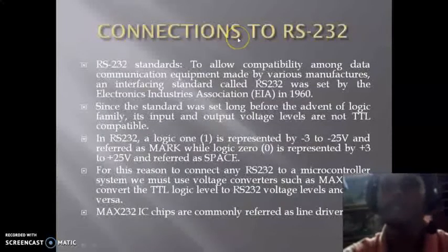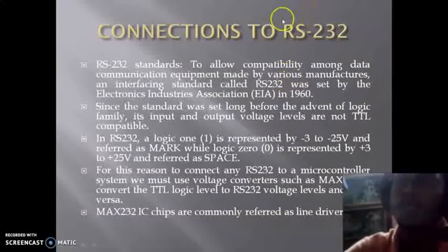Next I'm going to discuss something very important, that is the connections to RS-232. This is basically a standard. To allow compatibility among data communication equipment made by various manufacturers, an interfacing standard called RS-232 was set by the Electronics Industries Association, that is EIA, in 1960. Since this standard was set long before the logic family, its input and output voltage levels are not TTL compatible.